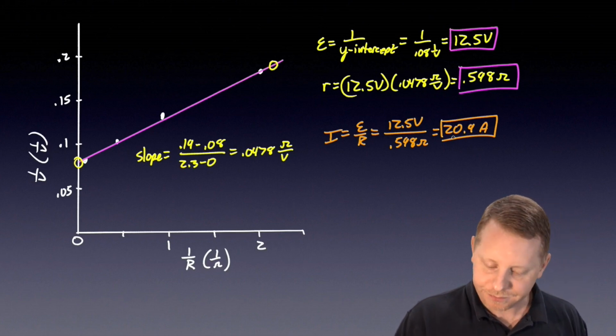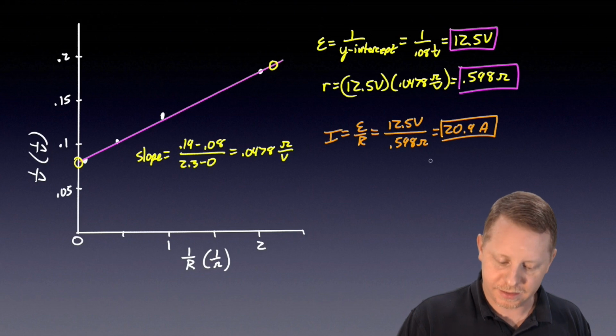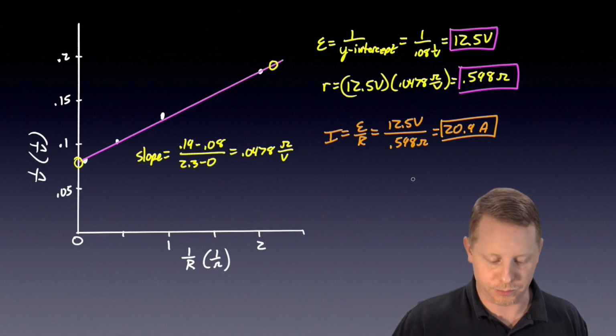All right. One more here. Let's go to the next page to give ourselves a little bit of room. A voltmeter is to be used to determine the EMF of the battery after removing the battery from the circuit. Two voltmeters are available, one with low internal resistance, one with high internal resistance. Which will provide the most accurate measurement? Well, now, of course, you want the voltmeter with high resistance.